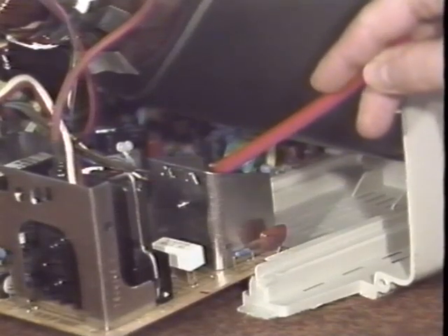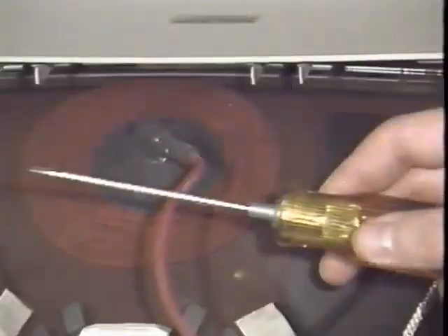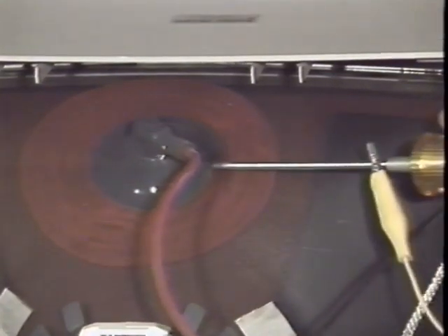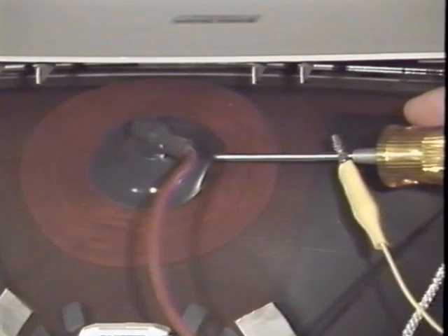When servicing a monitor, there are a number of things you must not touch. These include the anode and anode lead, which develop a DC voltage of several thousand volts. The yoke coils and the horizontal output transistor, which may produce as much as 1000 volts, and any large capacitors on the board should be avoided as well. Also, discharge the CRT and any high voltage capacitors before doing any soldering, resistance measurements, or other handling of the internal parts of the monitor.